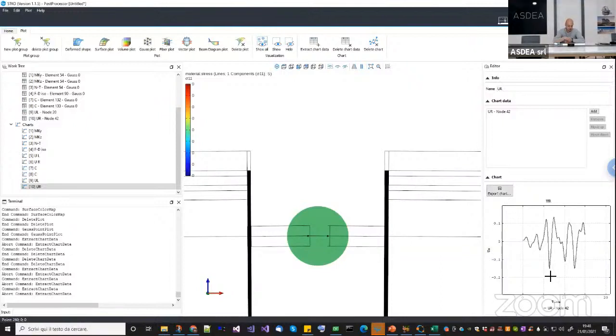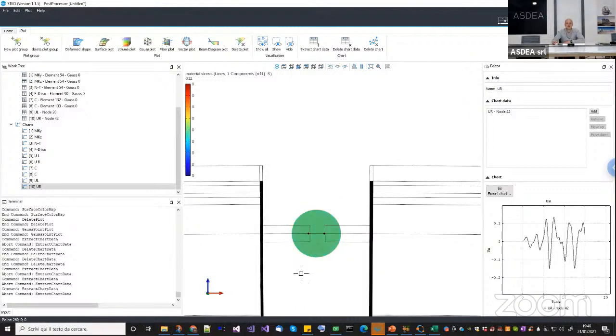Now, this allows me to introduce the last part of the webinar, which is explicit dynamics. What you've seen here is that this kind of analysis can be easily done with implicit time schemes. Of course, you may have convergence problems, but if you have properly set all the convergence tests, and if you use an adaptive time step, you can easily try to go through the convergence issues. The problem is that when you add strong nonlinearities like contact, okay, you have seen that it soon makes the convergence much more difficult to overcome, okay?